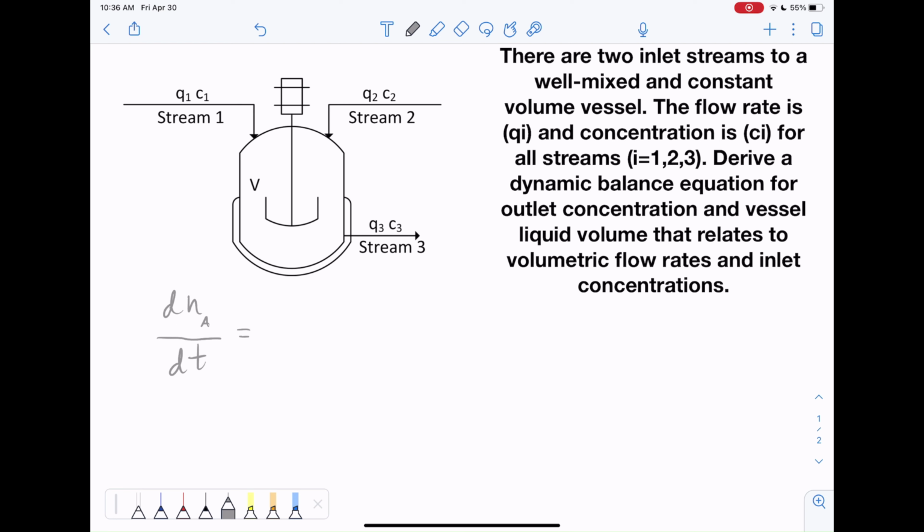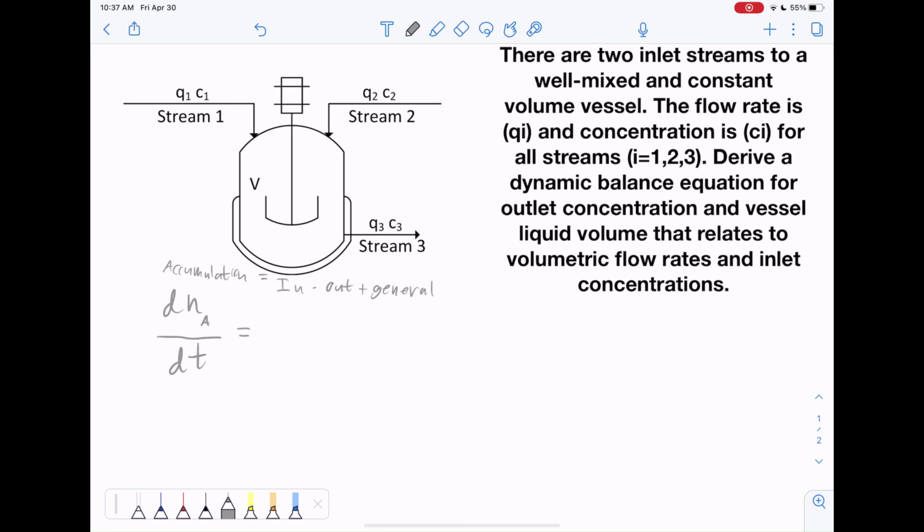And we'll start with a species balance. We can then move on to a concentration balance or a mass balance if needed. But we'll start with that. Very simply, if we think of accumulation, here we have our accumulation term, and since we're just doing a mixture, no sort of reaction, we won't have any generation or consumption, so it should just be in minus out.